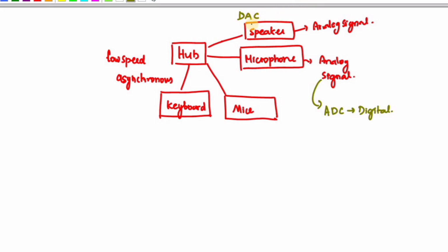Like the sound wave, we can process video information. Whatever data is processed by the processors should be in digital format, so it should have a sampling rate. That is, the sampling rate must be at least twice the highest frequency. The sampling process, which yields a continuous stream of digitized samples that arrive at regular intervals, must be synchronized with the sampling clock.